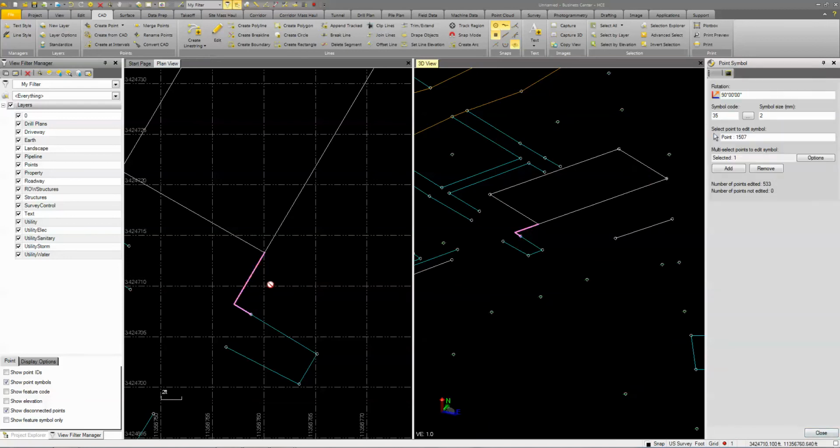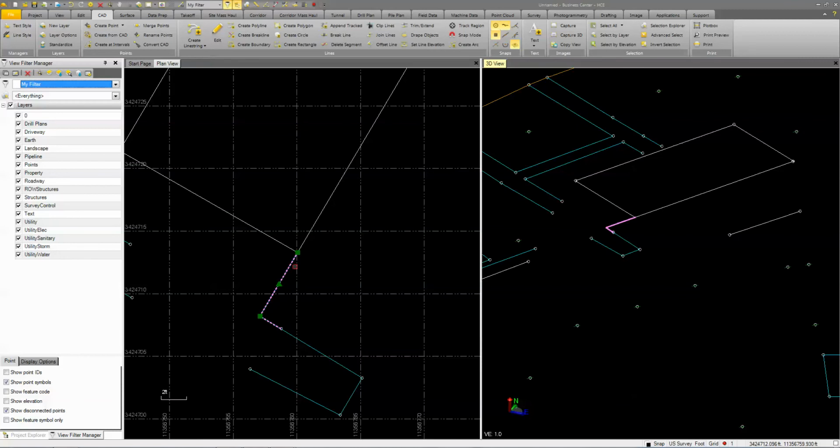Now with that, if I was to come in, let me close this. You'll notice that when the line is selected, depending on which segment I select, it's going to add the grips. It's not adding grips to these because those were drawn by those lines. But if I grab this one, I can take this grip, left click and hold, and drag it to a new location. I can come over here and drag it right back. If I grab the triangle, I'm able to move that whole segment accordingly. Then do a Control Z to send it back, or an undo.